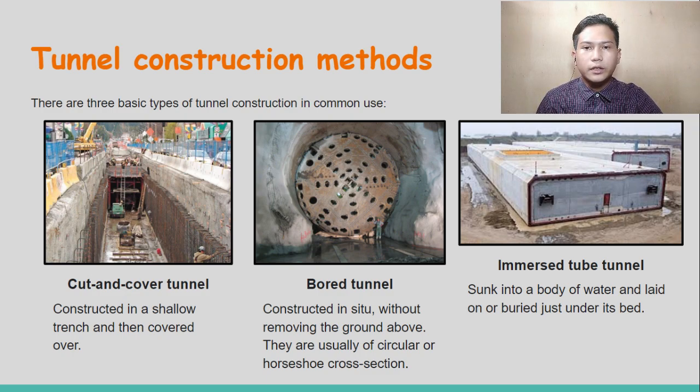Next is the bored tunnel method. The construction was constructed in situ without removing the ground above. Usually, this kind of method is suitable for the circular shape of tunnels. The last one is the immersed tube tunnel method, suitable for underground tunnel construction. The precast concrete will be sunk into water and laid on or buried just under its bed.